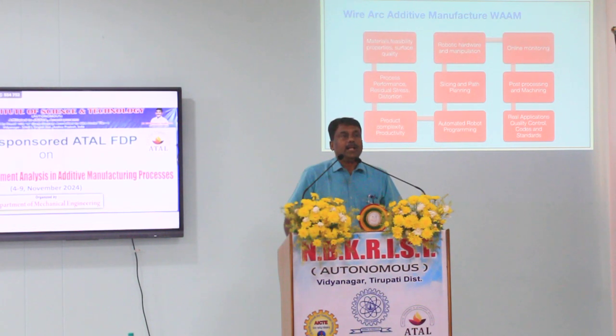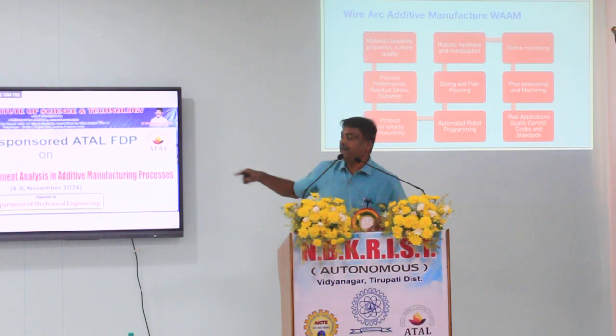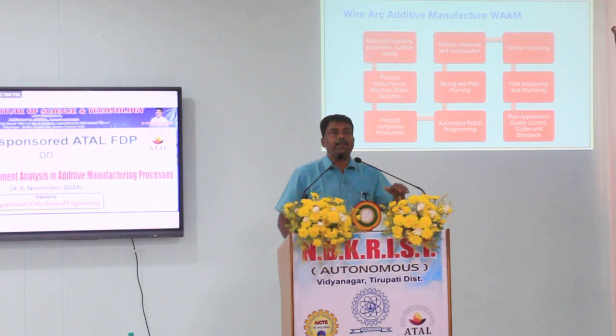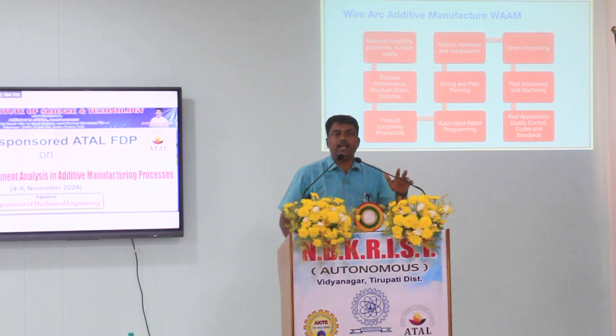Okay, so I will show a nice example of FEM in additive manufacturing. It is the major step we carry out once we arrive at the material and process. Suppose we decide to go for tandem MIG, doing this kind of deposition: how is the part going to evolve, is distortion going to happen, if distortion is there how can we mitigate it, and how is the temperature gradient going to evolve? I will come back to that.